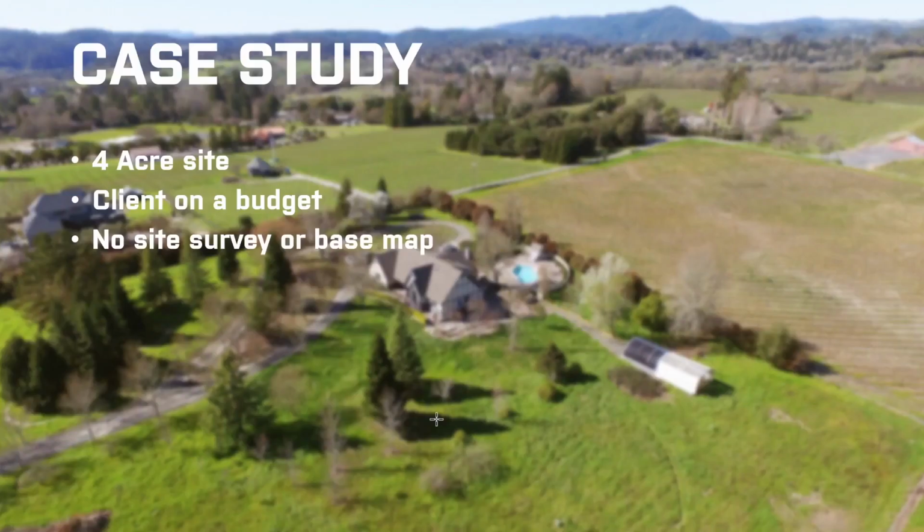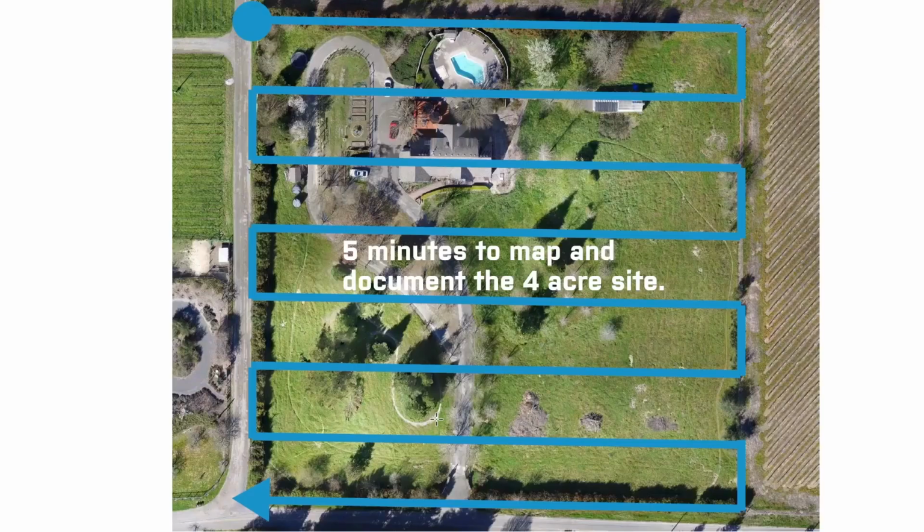So here's a case study of how I actually used a drone for a project site. This was a site in Forestville in Northern California. It was a 4-acre site. The client was on a budget. They didn't have a site survey or a base map of any kind, so we were just working with what they had as a property. So I thought this would be a perfect time to actually use a drone, and it was actually a perfect candidate because there are deciduous trees, so you could actually 3D map everything.